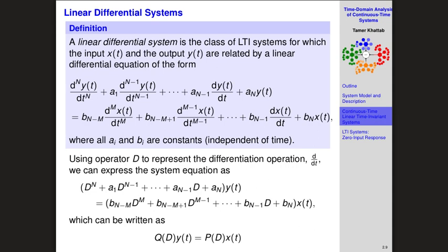Why? Because the output is not dependent on the input, it's dependent on the derivative of the input. And in case of quick change, this means that even though the input value is not big, but it changes quickly, you take the derivative, you get an output value which is blowing up to a very high value. So if it's an amplifier, it's going to saturate. If it is a motor, a DC motor specifically, it might actually break down just because of higher torque, and it just speeds up without any slowing down until it comes apart, and so on, right?